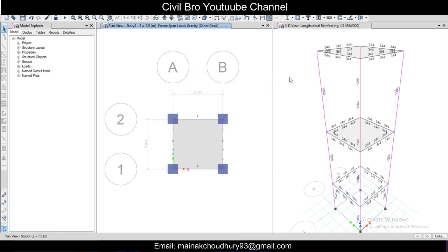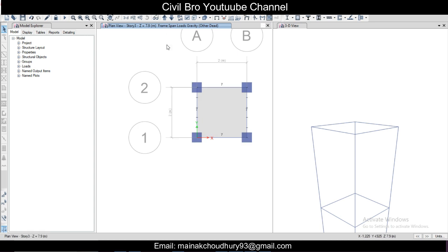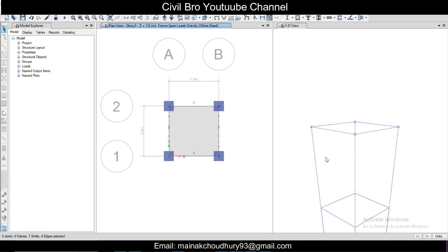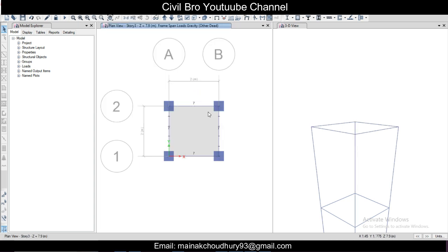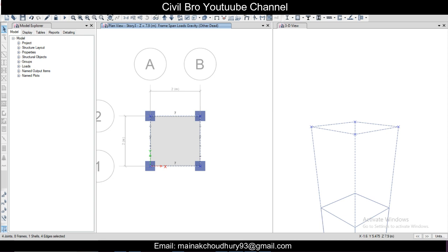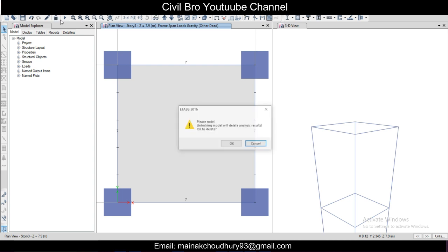So now we need to apply hinges. We apply the hinges on beams and columns just for the time history method. So first of all, let's apply to the beams. Before that, I think we forgot to assign the diaphragm, so we'll just redo it. So story 3, we'll select story 3 here, like this, and then go to assign joints, right? So let's first unlock the design. Okay,